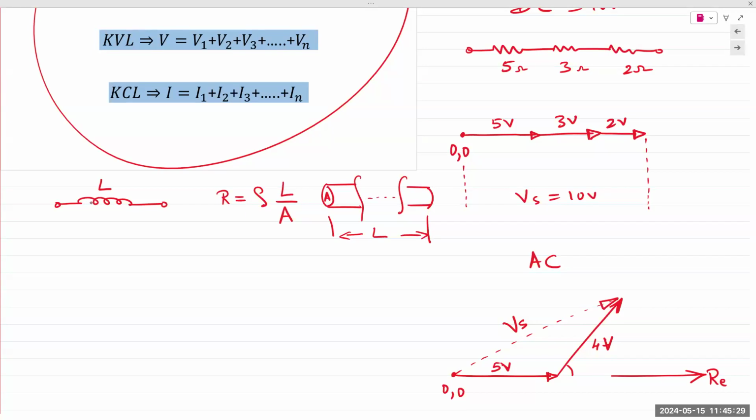So if you have an inductor that has a large number of turns, like 1,000 turns, if you unwind that coil and stretch it out, it's going to be a very thin wire running for tens of meters, maybe even hundreds of meters, perhaps, right? Very long. As you see in the equation, resistance is directly proportional to the length and inversely proportional to the area. Area is the cross-sectional area of that wire.